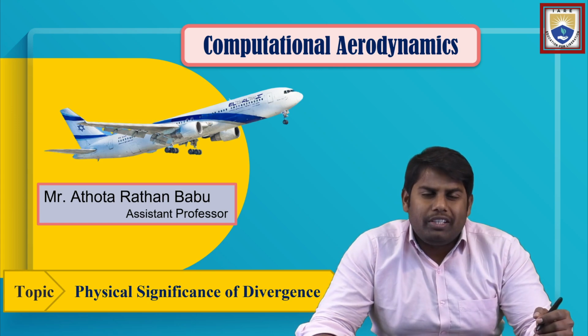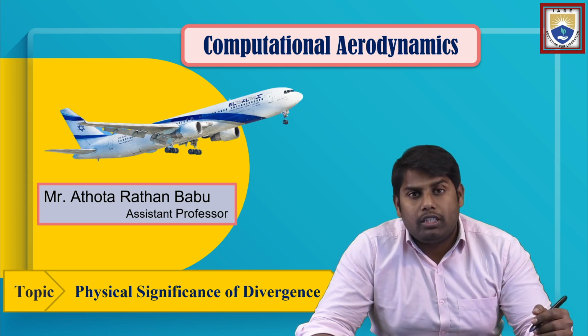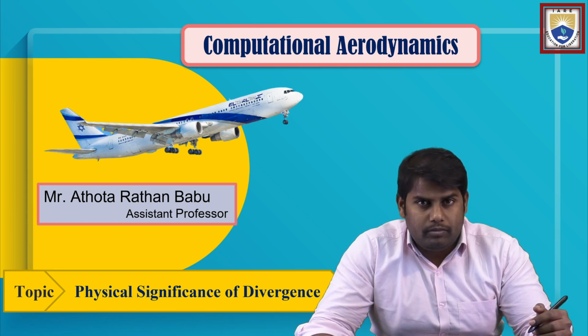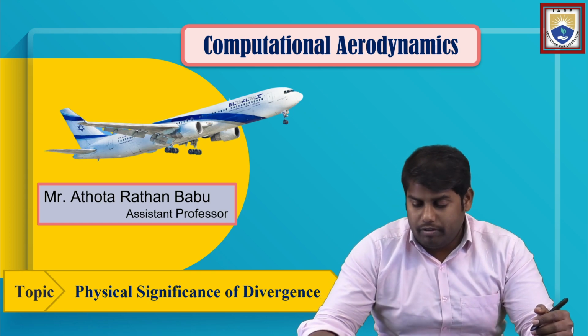Actually, so basically, what is divergence? So here we'll see in detail what is the divergence of velocity and how we relate the divergence with respect to any fluid element or a control volume which is moving with respect to space. Before knowing this divergence, let's see some vector entities, and we'll recall what divergence is.